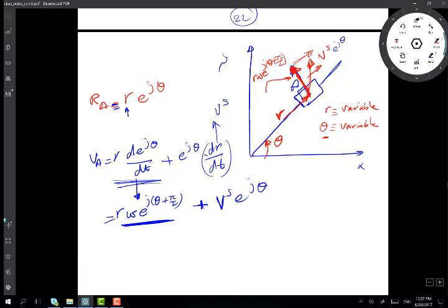So this is what we get when we have a condition such as this. This is the sliding over here, and the sum, this vector here, will give me the actual velocity of point A. It combines both the sliding velocity and the rotational term.